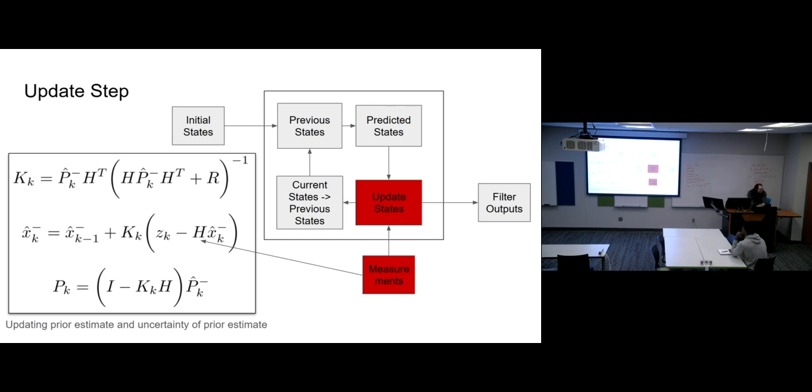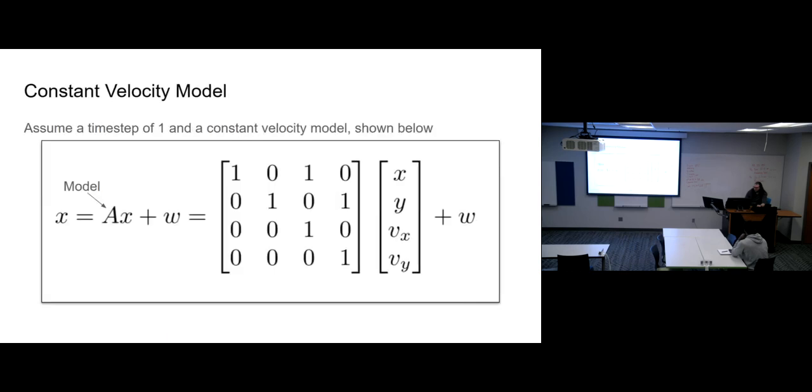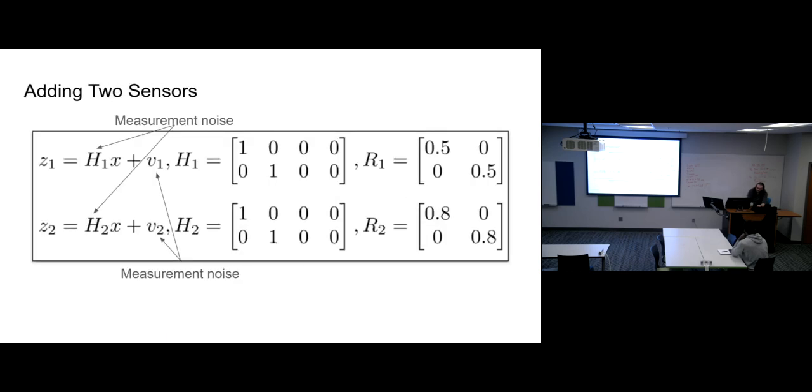And from a design perspective, if you're trying to build up a Kalman filter, you'll need to know these errors. With regards to getting errors for any given sensor, 90% of the time, you can open its data sheet and its error will be there, and you can just plug that in, and that's great. But if all else fails, you can simply make 100 measurements and compare them against a source of truth and compute your average error. Excel is very good for that.